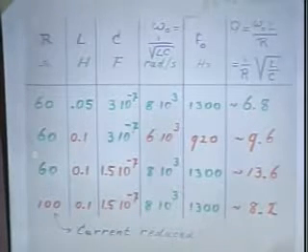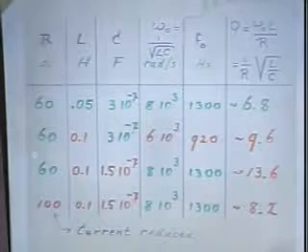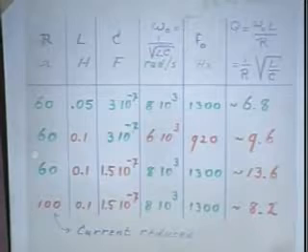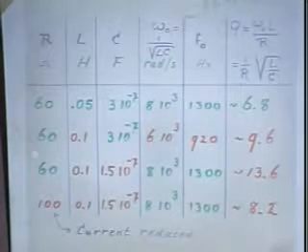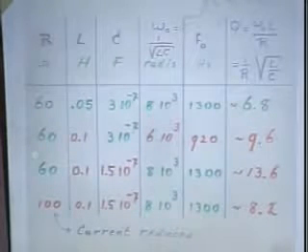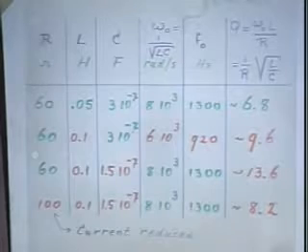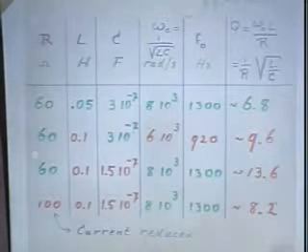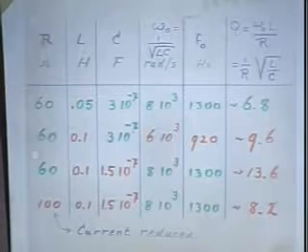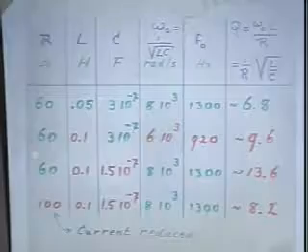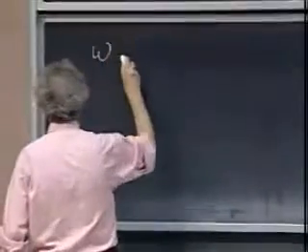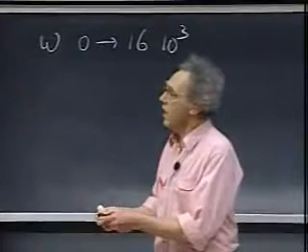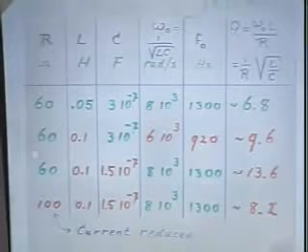The idea being that for these values that I have there, in the first line you see R, 60 ohms, and the self-inductance is 50 millihenry, and the capacitance is 0.3 microfarads. So that's a given there. And I give you here the resonance frequency, 8,000, in terms of omega, radians per second. This is the resonance frequency in hertz. And just in case you're interested, I give you the Q value there as well. What I'm going to do now is sweep the input frequency from 0 to 16,000 radians per second. So my omega can go from 0 to 16,000. I leave the values as they are here, and I'm going to sweep over this 8,000.